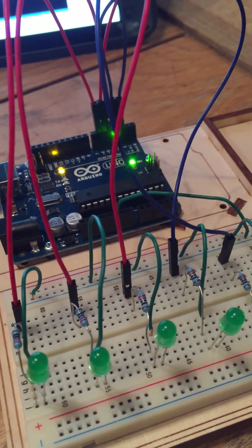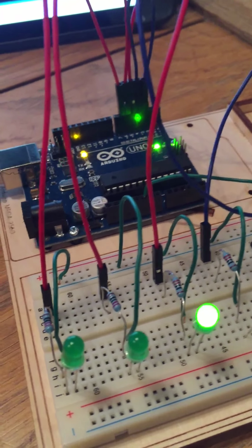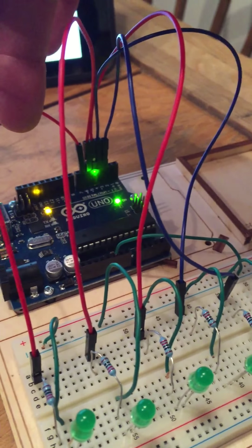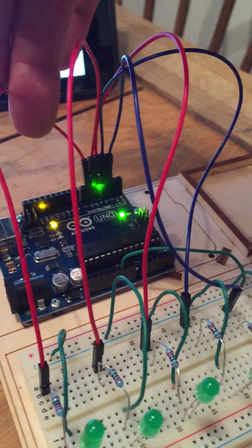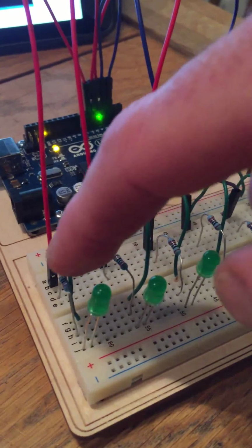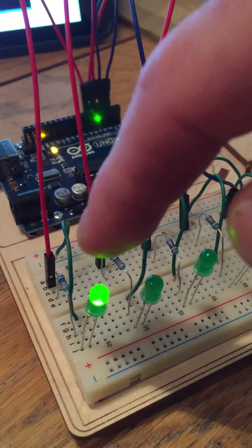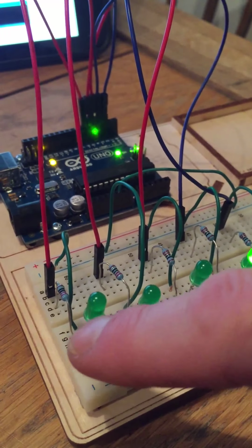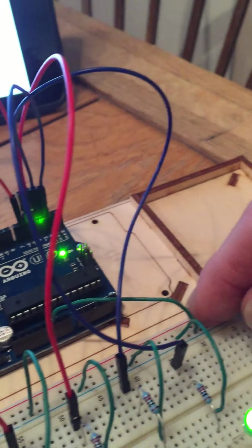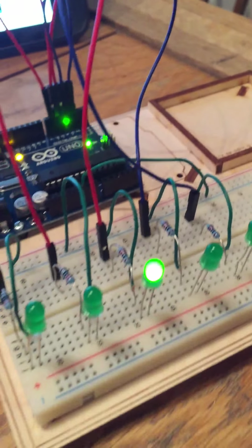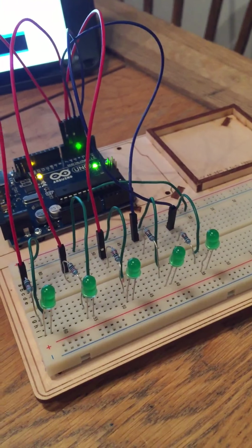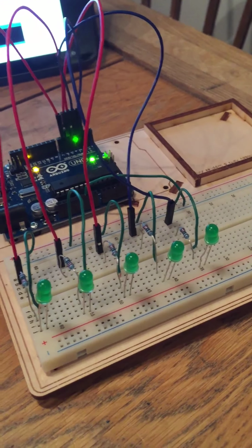They're all set as output, so if I just run through one, maybe that's pin 6, yeah, 6, set as output, the juice is coming in through the little 220 ohm resistor there, into the positive leg of the LED, and then grounding back. So that's just repeated 5 times, and as you can see, they're just flashing 3 times and looping through.